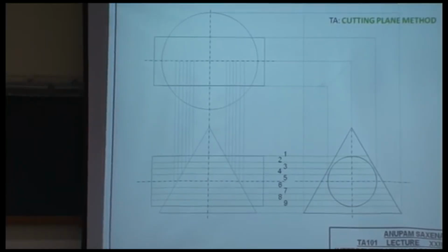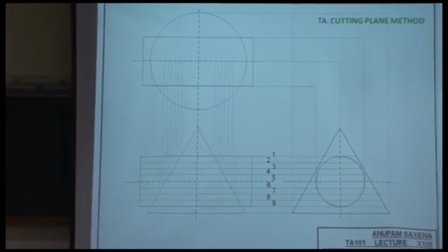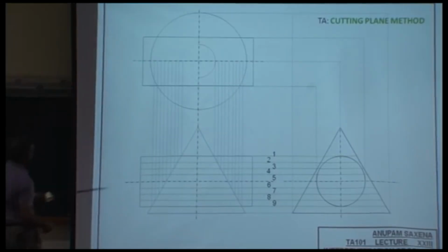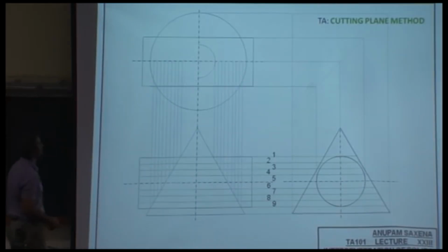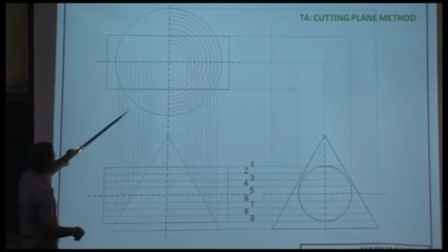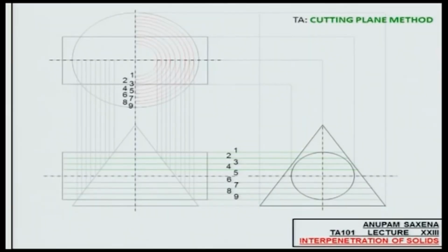You guys are dozing off. As a what? Great. So each plane will intersect the cone at a circle. Sketch those circles in the top view, and of course, don't forget to name or number those circles. From inside to outside, they are numbered 1, 2, 3, 4, 5, 6, 7, 8, 9.